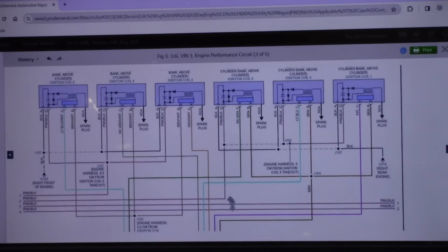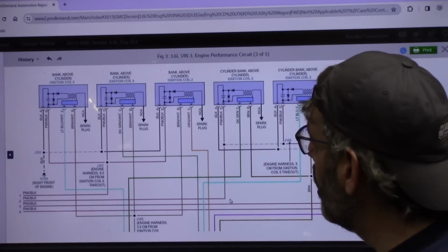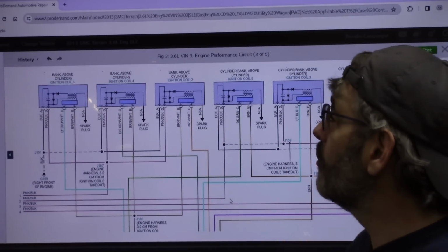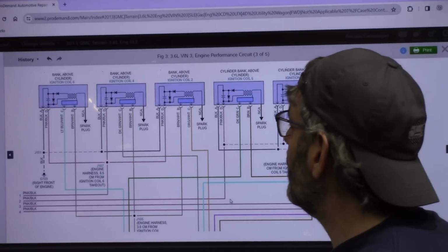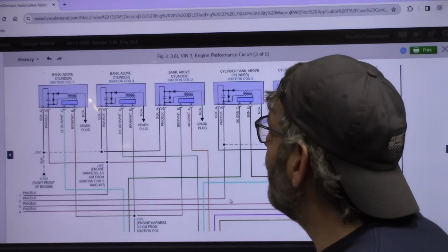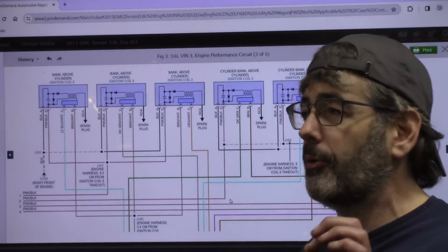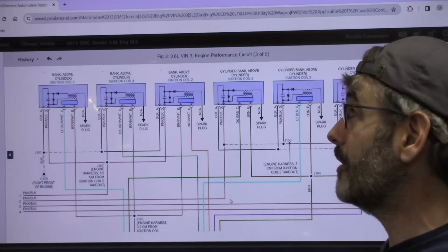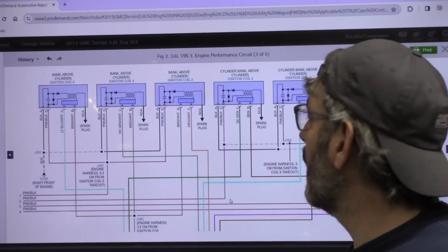Oh, well, actually, this may be cheating a little bit, but the ignition coils, this kind of does everything that I want because technically, I'm going to argue it's power side switched, but it's a little bit iffy because it's power side switched through a transistor, which I still believe is power side switched. And it would give us that real nice square wave that I think we kind of want to see.